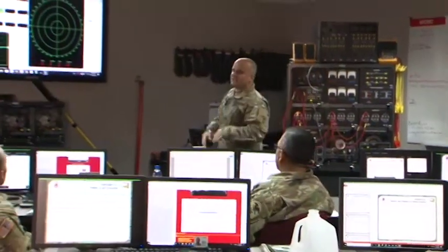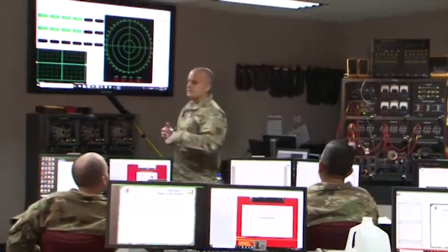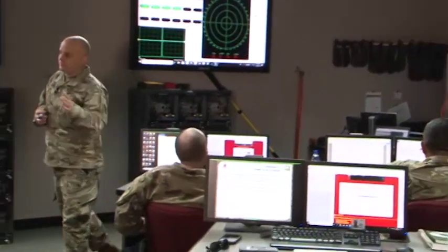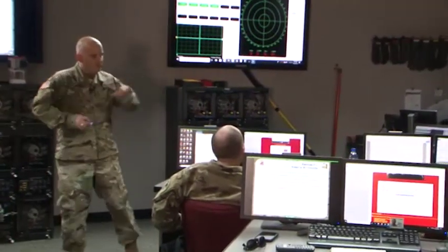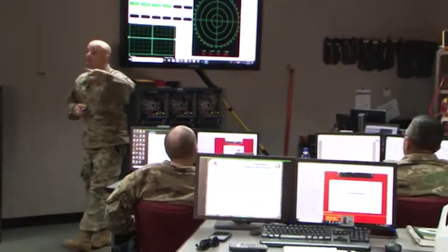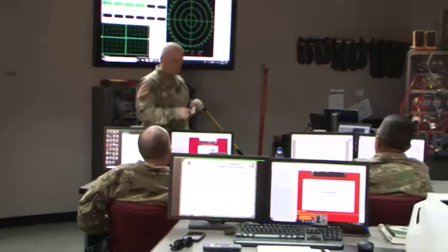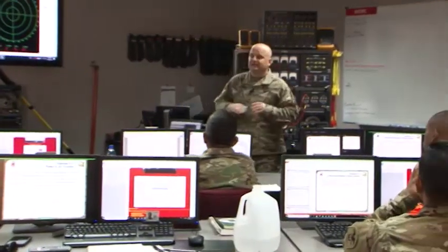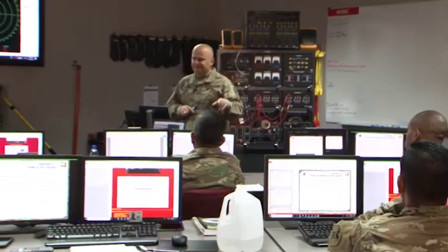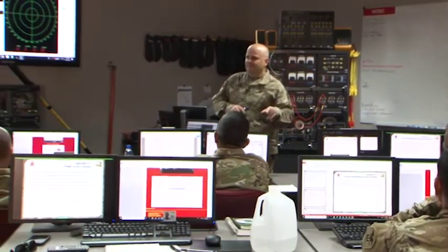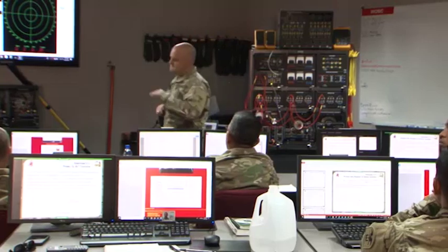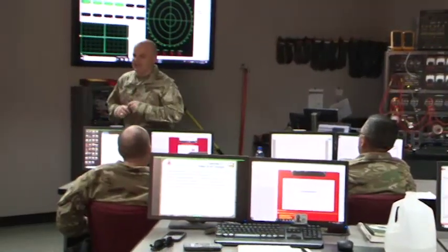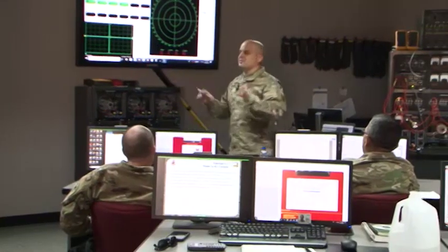Okay, so understanding the angular differences between voltage and current with inductive circuits, what is the angular difference between voltage and current? What is it? 90 degrees. Inductive, yes. 90 degrees? Okay, so that means if I have nothing but inductance, is it exactly 90? No, because we're going to have a little power triangle here. It's minute, very minute, but you're going to have a little power triangle here. But for all intents and purposes, we'll say 90.